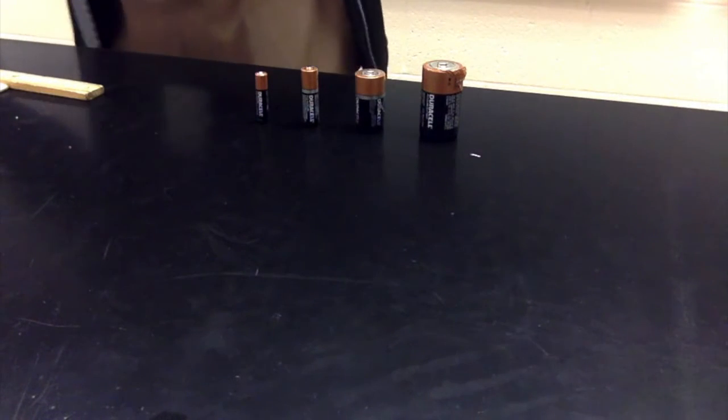Age means you just keep it there and you're not using it at all. The electrolyte solidifies, and that solidification prevents the ions from moving freely. That is what happens with age. So you may take a fresh pack that is 5 years old and try to use it in a flashlight, and the flashlight is not working properly. The reason behind it is the internal resistance has gone up.